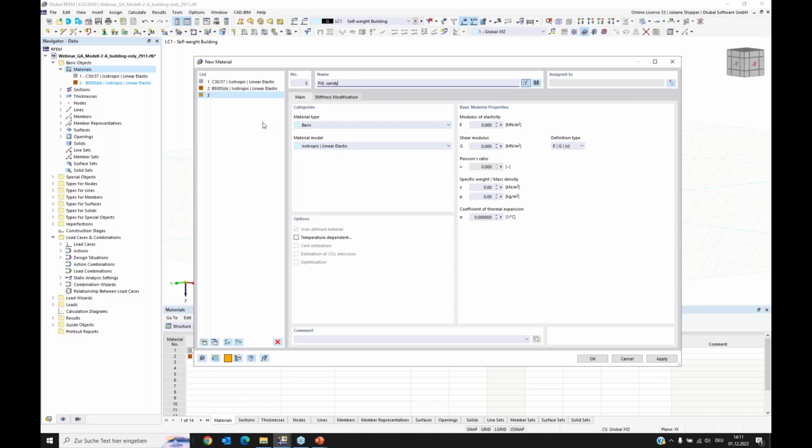and this is the name of the material, and what we need to edit is the material type. Here we have soil provided, and we need to set here the soil material type. Only if soil is selected, the specific soil material models are provided. As I said in the last webinar, I used the modified Mohr-Coulomb. Today we will use the nonlinear elastic model.